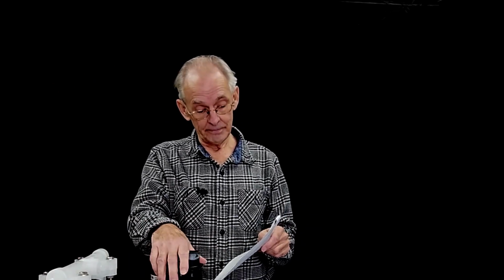So when you're picking this pump, you're saying, well, I need 20 gallons a minute from the bottom of a 10-foot tank, and I have to lift 5 more feet above that. So I need 15 feet of head at 20 gallons a minute. So you pick a pump that will produce that.